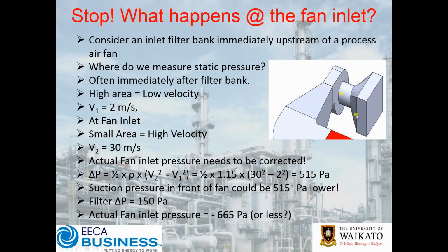If you're taking measurements here, and I certainly see a lot of facilities where the measuring point is here rather than right at the throat of the fan, you need to be very, very careful to understand what's actually going on with the system. Another point to consider is that you might also have additional variation due to other parts of the system impacting on what's going on. So you need to be very careful when measuring these pressures that you understand what's going on and that you've compensated correctly.